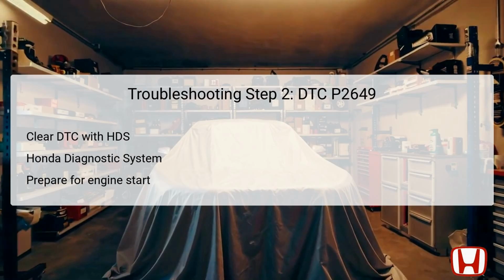After recording the necessary diagnostic data in the first step, the next action is to clear the DTC using the Honda Diagnostic System, HDS. The HDS is a specialized tool for Honda vehicles, which allows technicians to read and clear DTCs effectively. Once the DTC is cleared, the technician should prepare to start the engine. This preparatory phase is crucial, as it sets the stage for testing the vehicle's performance under conditions that might reproduce the error. Clearing the DTC allows for a fresh start, ensuring that any subsequent readings reflect the current state of the vehicle components properly.